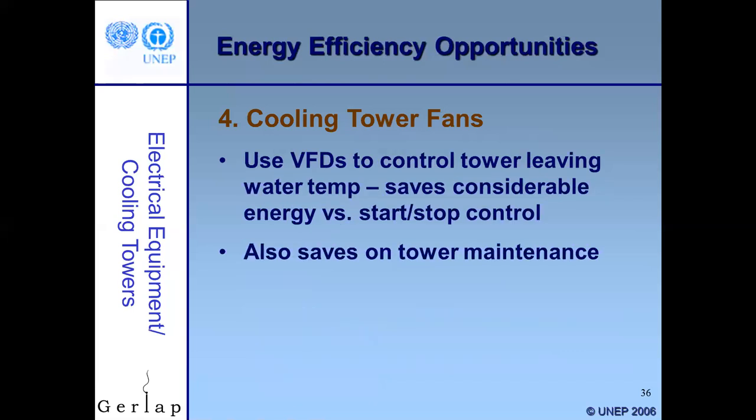And these days, we're seeing a lot of conversion of tower fan control from start-stop or two-speed motors to just variable frequency drives. Saves a lot of energy. Major retrofits are going on across the country, across the world. The VFDs also save a lot on maintenance, because if you've been running start-stop, you're starting and stopping that motor hundreds of times a month, and it just causes things to fail. So the VFD can start and stop if it needs to, or just modulate speed. It starts very slowly, winds up, and doesn't cause a problem. And that's what the video link that I'm supplying with this will talk about.